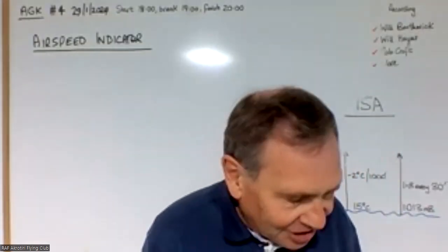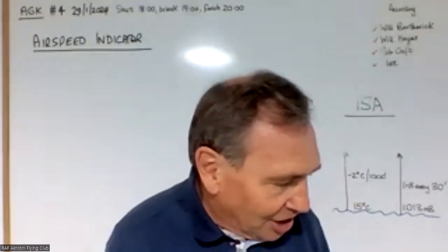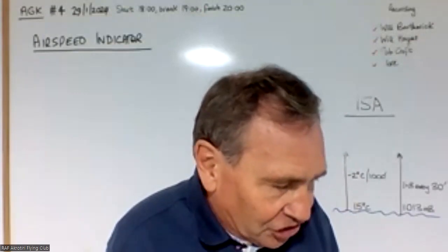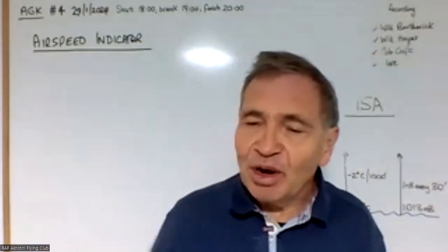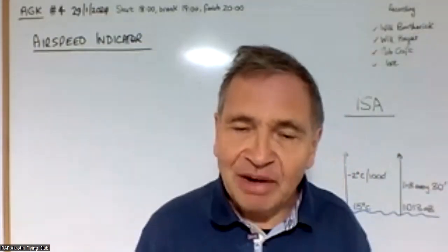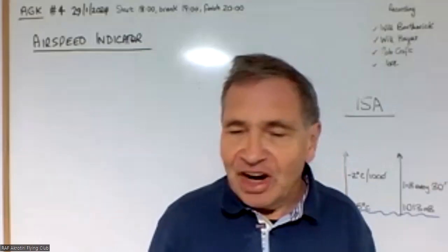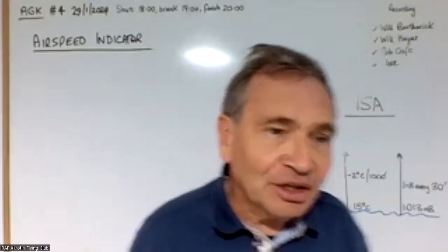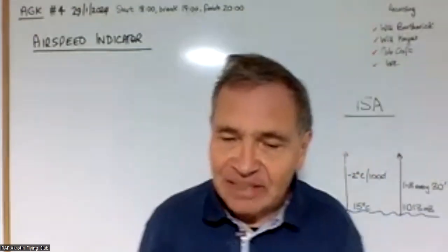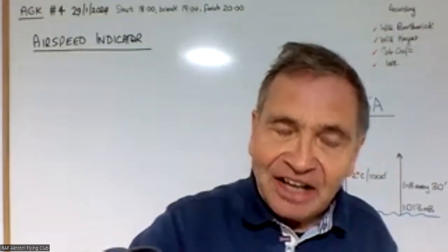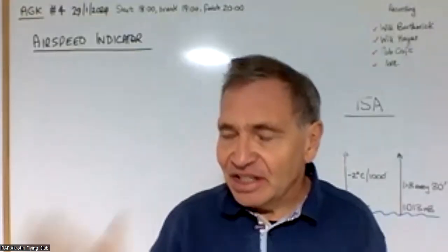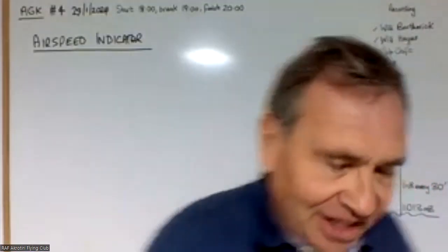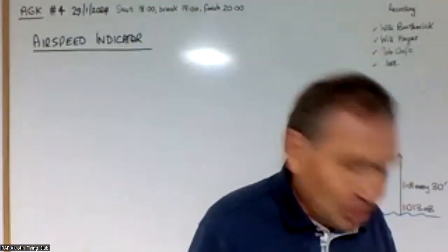So that's a typical test of a good pilot, and your instructor will expect you to do that as you apply power and you start gathering speed down the runway. After about 5 or 10 seconds, he'll expect you to look at the airspeed indicator and just say "airspeed live." And if it's not live, bring the power back, bring the plane to a nice slow down, come off at the next intersection. It's not an emergency.